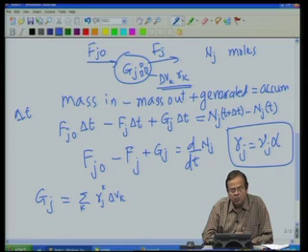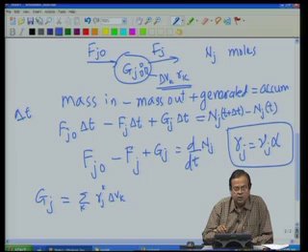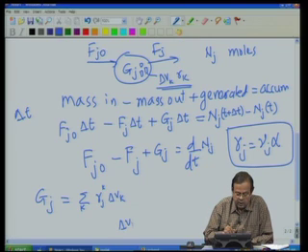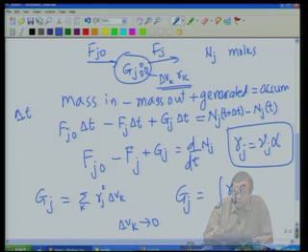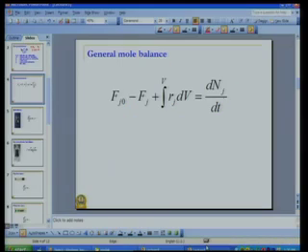Now, once again we can make these volume elements smaller and smaller, such that delta Vk tends to 0, then the summation of the series is converted into an integral, and what we have is Gj is integral Rj dV, that is integrated over the entire volume V, is my net rate of generation.